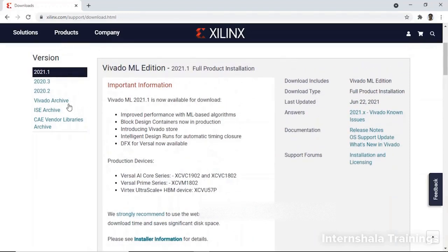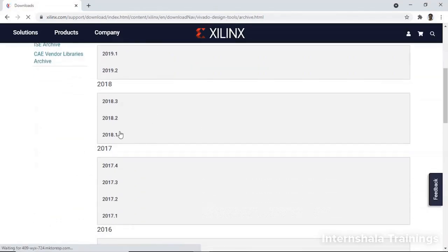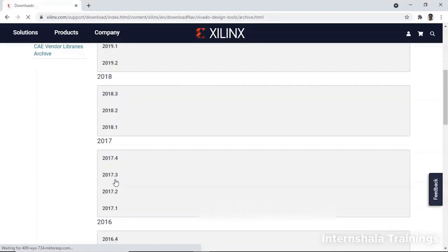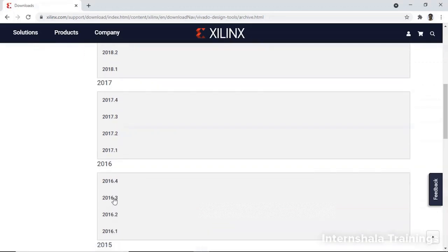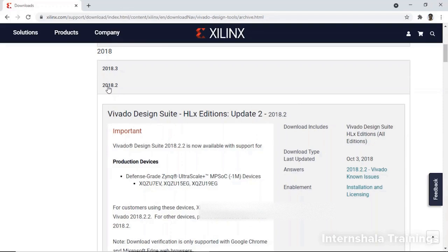So we are going to go to the Vivado archive, and here we can choose 2018, 2017, 16, anyone. Okay, all of them are fine with the size also and board compatibility also. So let us go to the latest among these, and I select 2018.2. There is not going to be much of a difference between these versions. Okay, so all the features are going to be mostly the same for the Webpack editions.